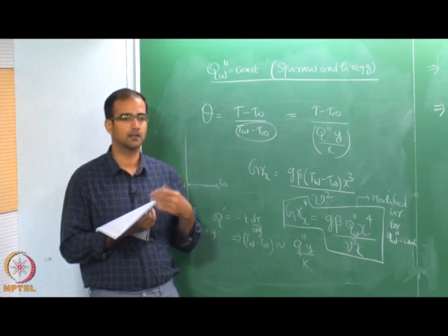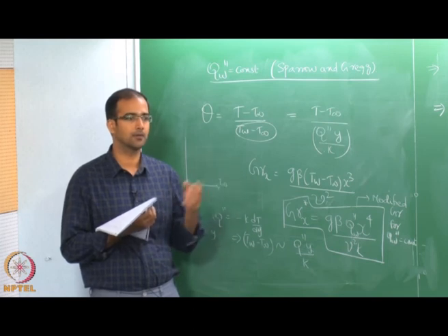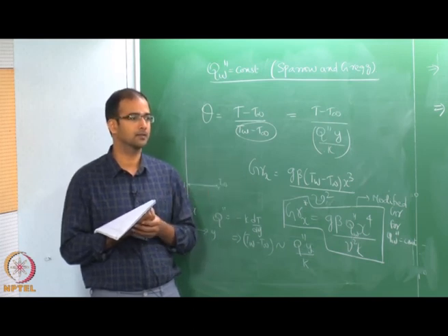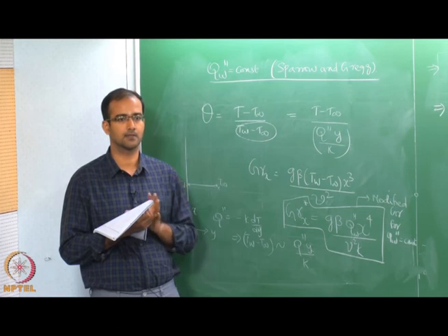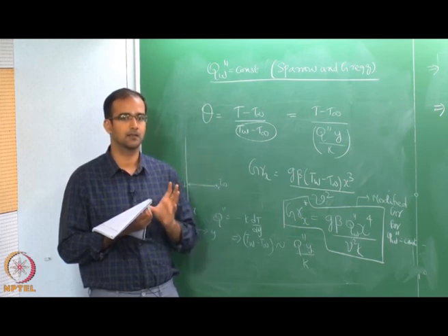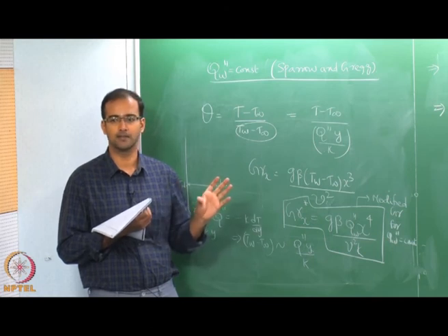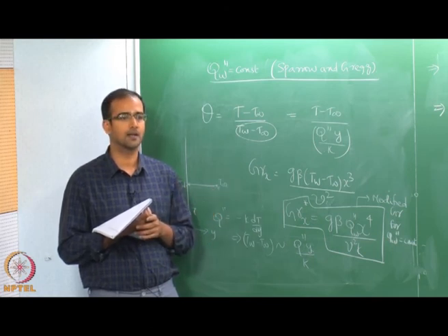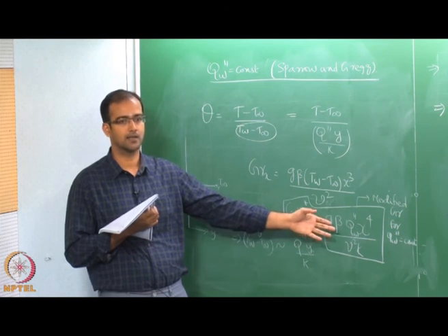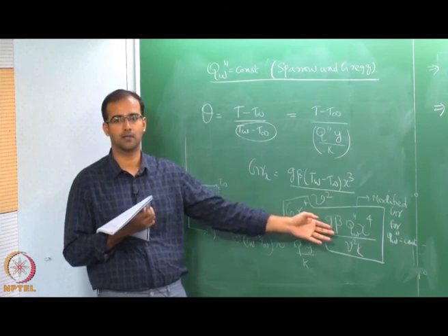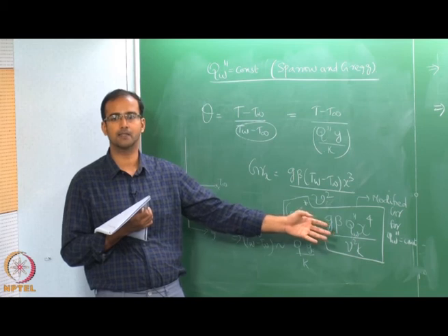Why should we use y times x? How do you then compute your Grashof? Is it a 2-dimensional variable? The Grashof number is just a local coordinate which is attached to the plate length. So, we cannot define a 2-dimensional Grashof number here, it is like defining a 2-dimensional Reynolds number. So, this is a definition. There is nothing wrong in defining a Grashof number the way you want it, provided it is dimensionally consistent.